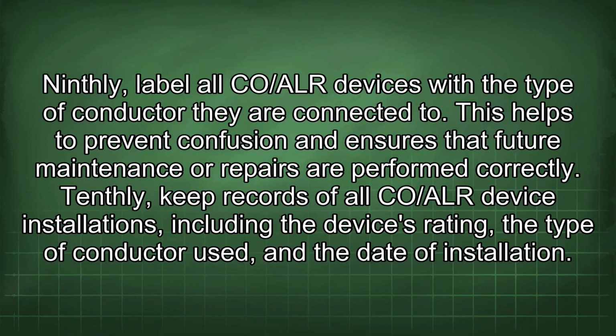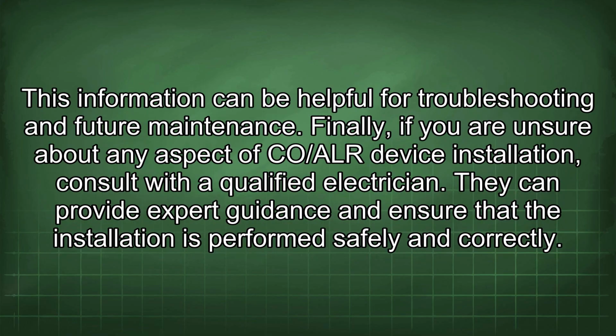This helps to prevent confusion and ensures that future maintenance or repairs are performed correctly. Tenthly, keep records of all CO/ALR device installations, including the device's rating, the type of conductor used, and the date of installation. This information can be helpful for troubleshooting and future maintenance.